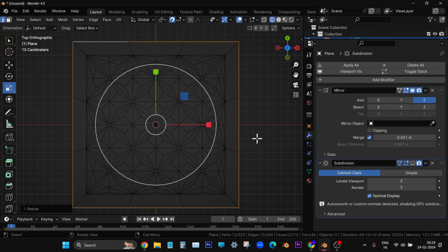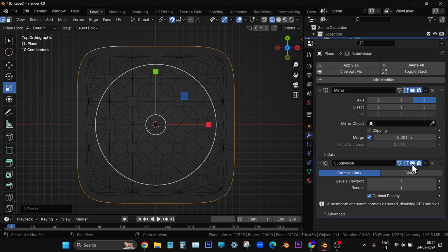That may change, maybe it is not reflecting immediately, but at least the amount of memory Blender is occupying will reduce. So they switch it off in the viewport and let the render be on, which is the last icon, the camera icon. In the render, let the modifiers show their result, but not in the viewport.